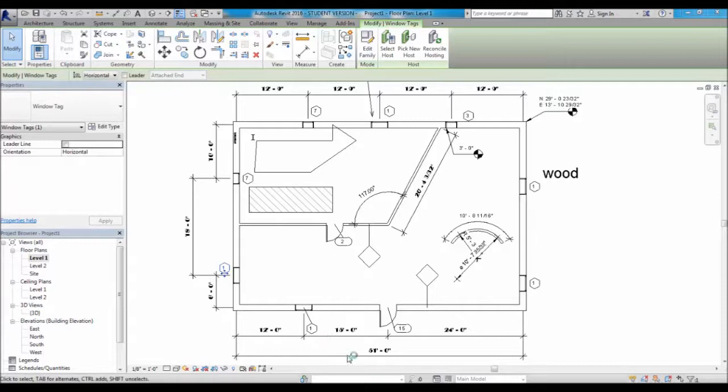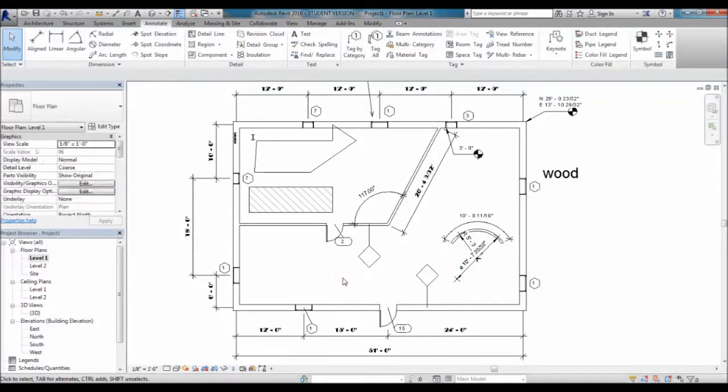So you're able to look at a plan and say this window here, this window here, this window here, as well as the window on top here, these are all window type 1s. You'd go and refer back to the window schedule and it would tell you window type 1 is this big and has this frame and so on and so forth. But you generally will see them called out only as the type of window, not by the individual window itself.